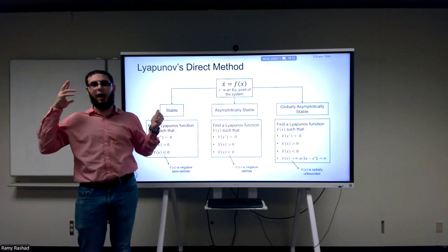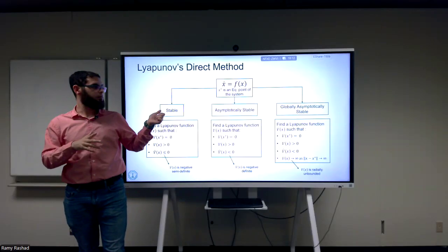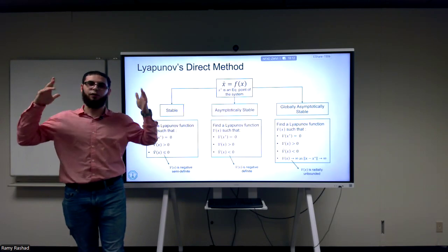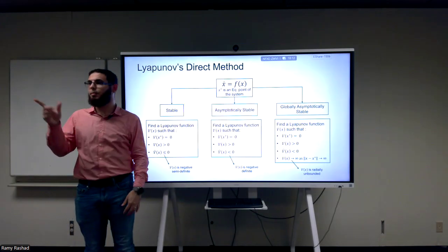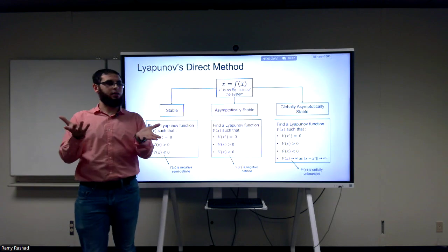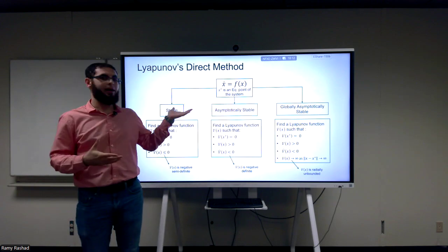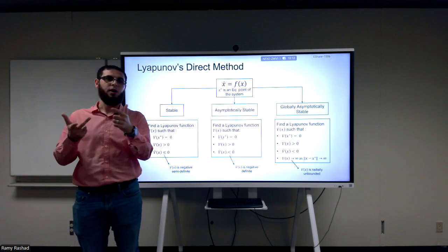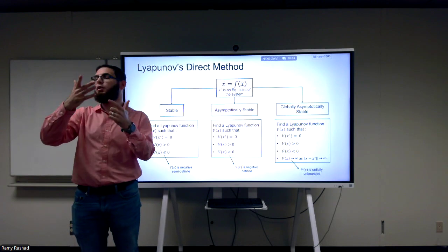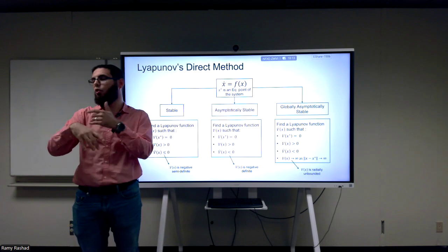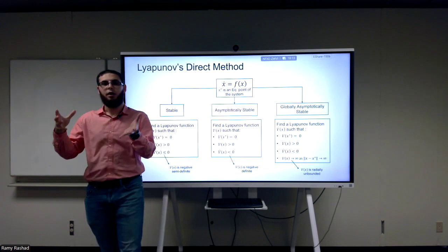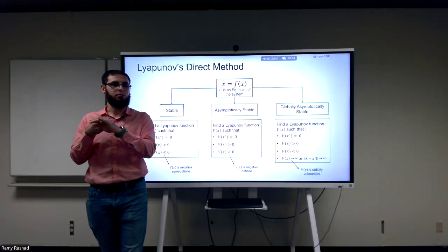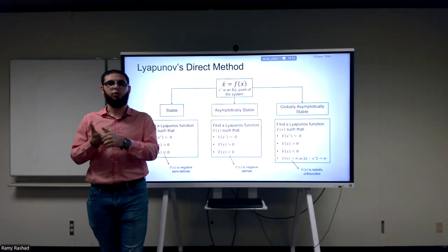First of all, again, what do you think the idea of this Lyapunov theory is? Where did Lyapunov get this idea from? From energy, exactly. Energy is a scalar quantity of the systems that we have. So I might have a mechanical system, which is the pendulum, or the mass spring damper system, or the N-link manipulator, or the floating base manipulator, or the MAV, whatever. All of these systems, because they are mechanical systems, have two types of energy. What are they? Kinetic energy and potential energy.